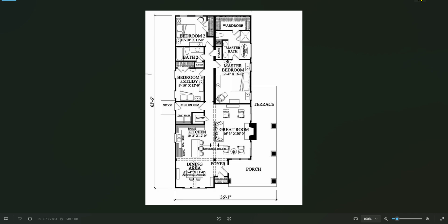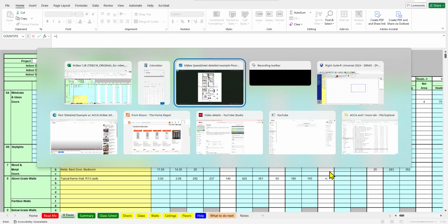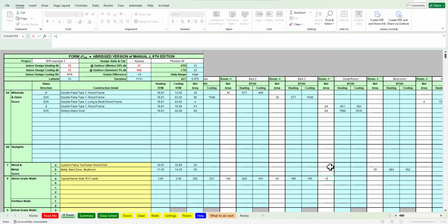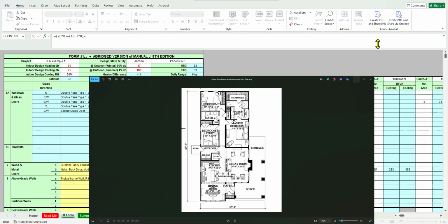Okay. All right. So we have here, where am I? Here we go. That's where I am. So we have equals. Oh gosh, I already forgot what the. Okay, 20 feet. So we have 20 feet times 8. Plus, we said that it was 2/3 of that 16-foot wall, so 10.7 times 8. Now we need to deduct. Right, so that's the 2 walls. That's that east wall over here. That's the 20, and this is 10.7. Okay, so we're adding them.